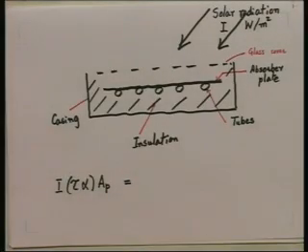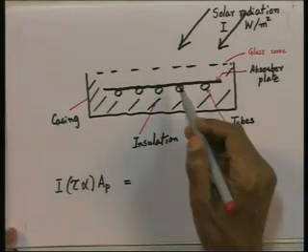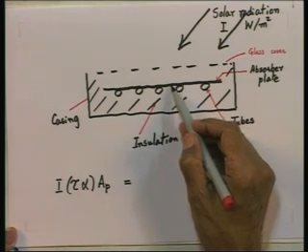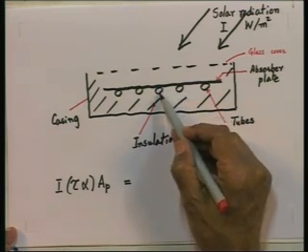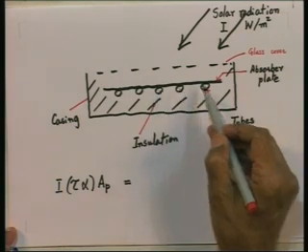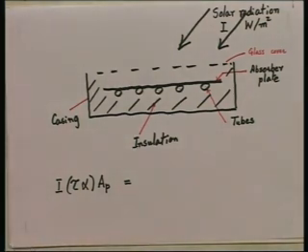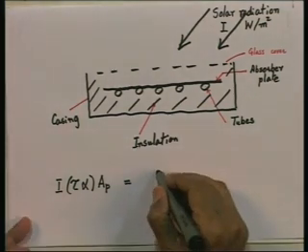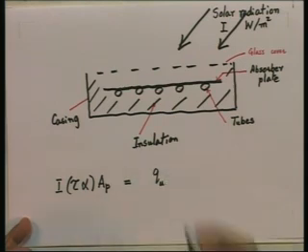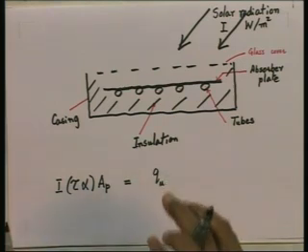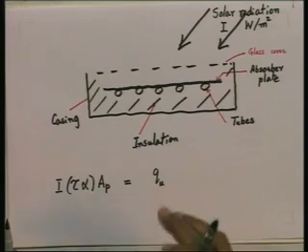Now, where does it go? The first place where this heat, which is absorbed in the absorber plate, goes is that it heats up the absorber plate, and then flows by convection as useful heat gain into the water which is flowing through these tubes. So, the first part is the useful heat gain, which I will call Q u, which is the heat gained by the water flowing through, and this is what the flat plate collector is there for. But in addition, we lose some energy.